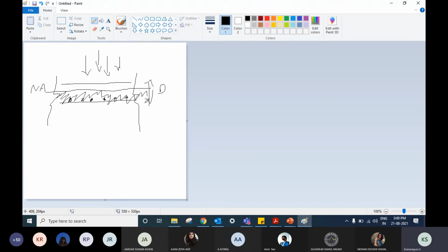Your overall depth is also very important for fire rating. Suppose you have a slab which is very thin, like 50 mm or something. First of all, it's going to deflect so much. Second thing is fire rating. If it starts to experience fire because of something, it needs to stand for a few hours.